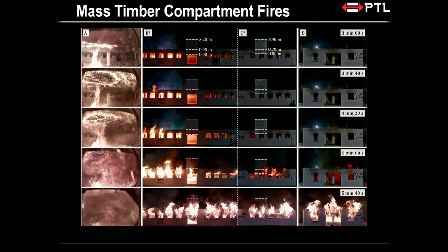So, compartment fire dynamics, especially traveling fire, is still a research sort of topic. So if you have a fire engineer proposing to you in your design that he or she is using traveling fire, you might want to second ask that a little bit, right? Because a lot of people might assume a localized fire, which is much weaker than what is happening in reality, right? So you don't want to get caught off during your detailed design that your char depth of 10, 15 mil is actually more like 50 or 60. That's the end of the structural design. Like, oh, your member sizing is wrong, okay? So just be a bit mindful on that.